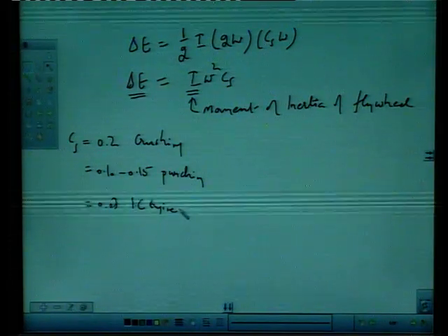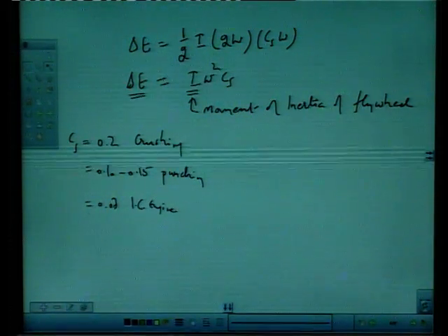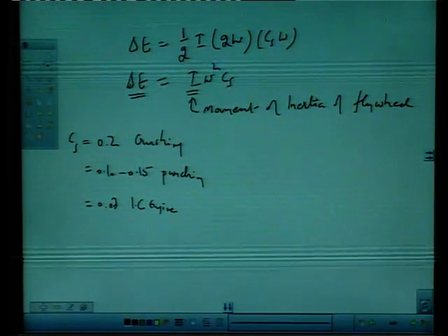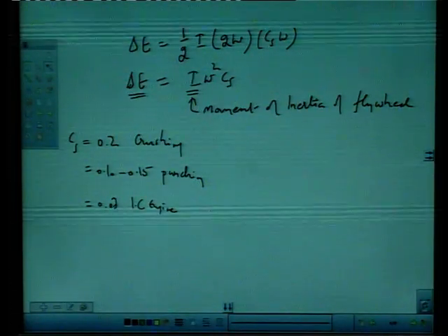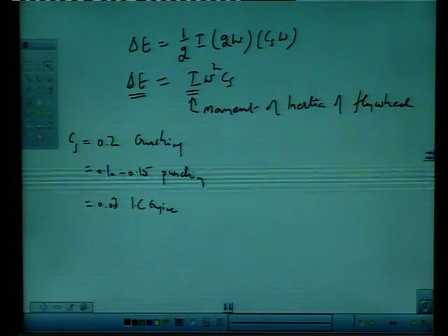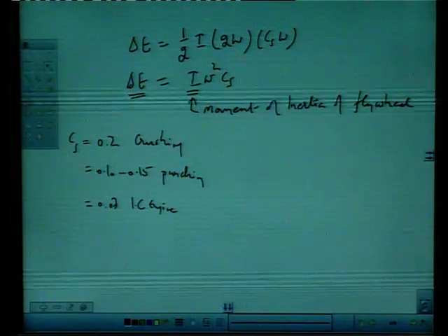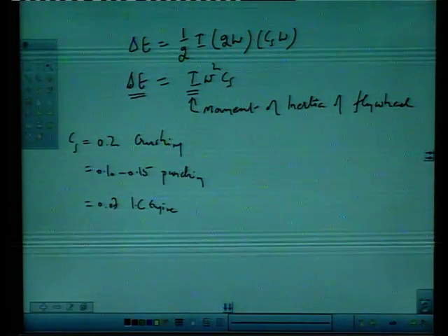Now, these coefficients are known to you, and this can be put in this equation, and mean angular velocity is known to you. If you can find the maximum fluctuation of energy, you can calculate the required moment of inertia of the flywheel from this equation, right.